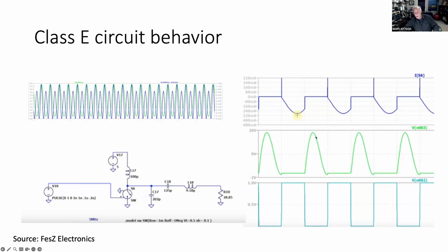But at the peak of voltage, the current is only there for a short time, so the amount of power is small. The current going through, if you look at the blue curve, is actually 0, because this is kind of a negative pulse of current here. So when the transistor is turned on, the current is practically 0 going through it, and then it goes through a rise when the transistor is off, which is kind of strange. But the main thing is that the current is either 0 or less than maximum during the transition from on to off and off to on. Combined with the fact that the voltage is 0 at the transition points, you get practically 0 power dissipation. So that's really it. I know it's kind of technical, but that's the essence of how these kinds of amplifiers behave and why they're so efficient.